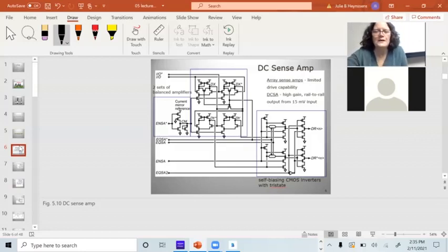Okay. So the DC sense amp that they're using now is not actually a latch. It's a little bit more complicated because they had to get the sensitivity up. But understanding the place of the sense amp in the circuitry was an amazing feat for undergrads coming in and getting hired, which Micron really likes. There could also be other circuits where you need a sense amp. We'll get to that later. Okay. So what we have here is 4 differential amplifiers.